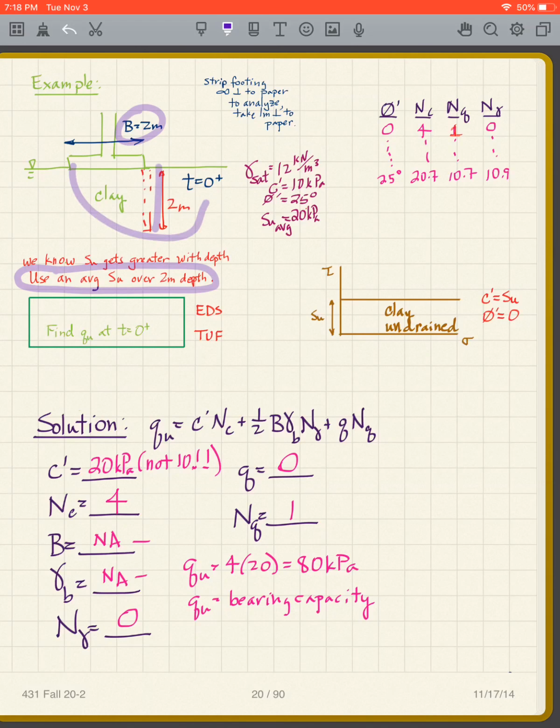We're expecting that it's this region of soil here that is going to be sheared. So in other words, we can develop a shear plane that goes something like that, and that means the soil here is sheared, here, here, across all these depths, we're going to be shearing the soil.